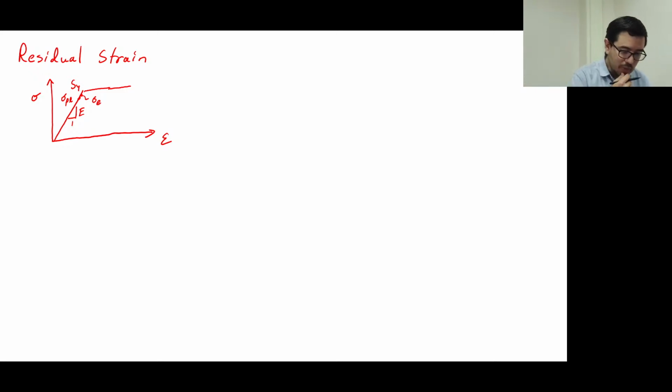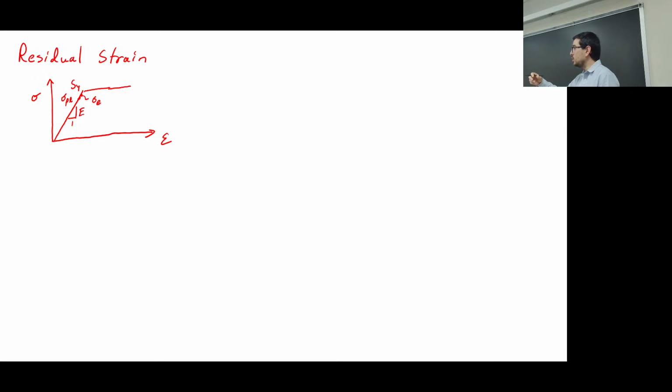Now, this is a linear elastic, perfectly plastic model, and something I didn't tell you yesterday is that if you go beyond the yield strength and you go over to the right, remember I did tell you that if it's perfectly flat, that suggests that you're getting a free lunch. In other words, you just get more and more strain without having to increase the amount of force. It's not really a free lunch. It's just that there's no longer a significant slope.